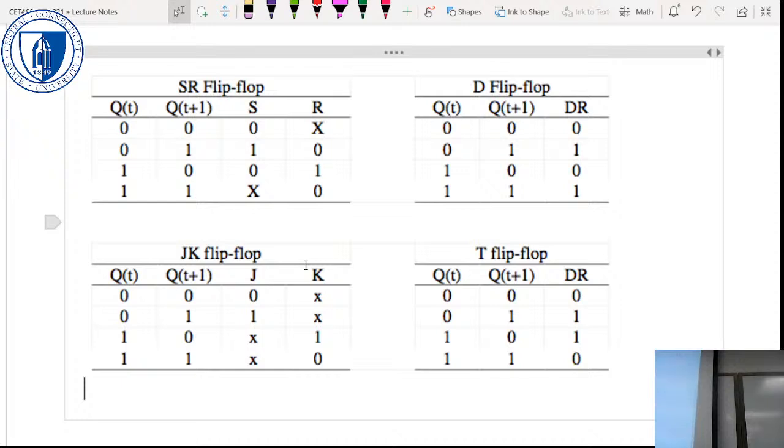And that's going to give me potentially a simpler circuit. Maybe not. The downside of this flip-flop over one of these two is these two only need to figure out one input. JK flip-flops I've got to figure out two, so I've got to have two logic functions.